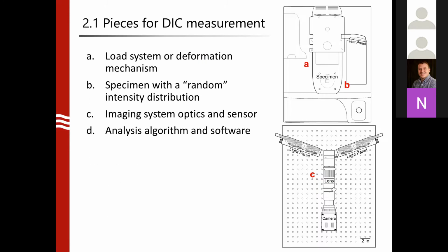here's one of those examples. This is what a typical DIC experiment setup is. You have a sample there under deformation, and then you have a specimen painted with the pattern, and you have a light source to give the lighting, and you have the high-speed camera to take the images. After all these images, you put them into some software or code to solve the deformations.